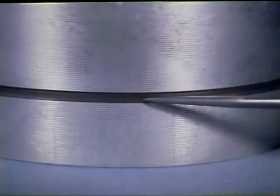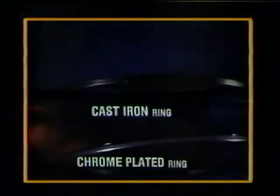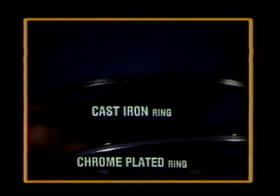Some pistons are also fitted with an oil wiper ring. This ring is on the bottom, which either wipes oil toward or away from the oil control ring, depending on the engine design. Piston rings must be carefully matched to the cylinders. This is done so that either the ring or the cylinder wall will wear just enough to form a good tight seal. Hard chrome-plated rings may be used in cylinders having plain steel barrels, but only plain cast iron rings may be used in chrome-plated or nitrided cylinders.